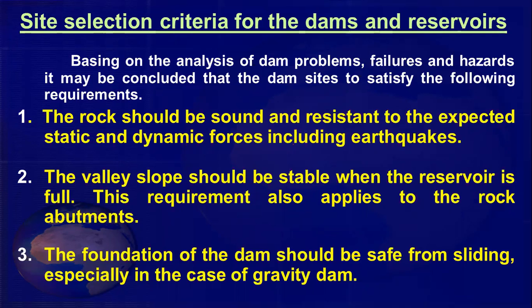So this requirement also applies to the rock abutments, because your valley will act as an abutment. On both sides, it will provide the support to your dam wall. Then the third point is the foundation of the dam should be safe from sliding.